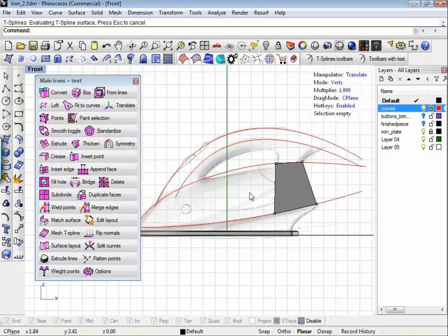By default, we're starting in smooth mode. I actually want to work in box mode, so with the heads-up display on, which I get by hitting the control and the space bar, which turns that on and off, I'm going to just hit the tab key, and that's going to switch me into box mode so that I can build this out of squares.